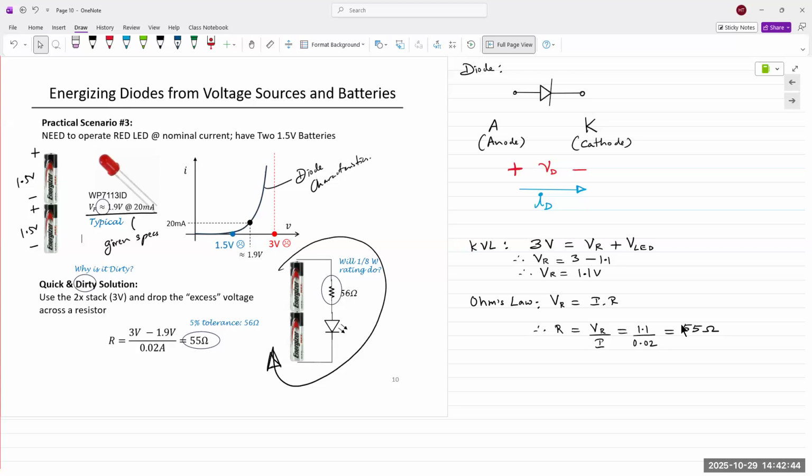These are small experiments that you can perform. In your lab kits, you also have LEDs. So you can take your LEDs and connect it to, I don't know, like a 100 ohm resistor and crank up the supply voltage to like 3, 4, 5, 6, 7, 8 volts. See how bright you can turn it on. If it blows out, I'll give you some new ones. I think you have like 1 or 2 LEDs in your lab kits. So if you blow one out, just let me know and I'll bring you some.